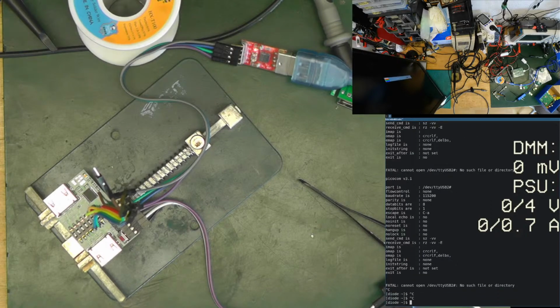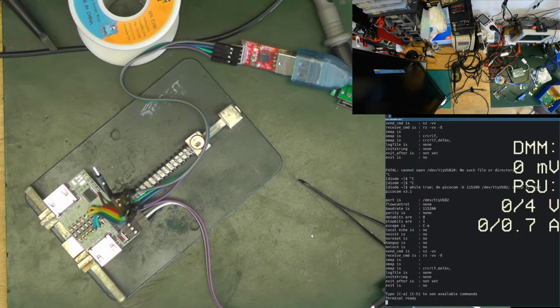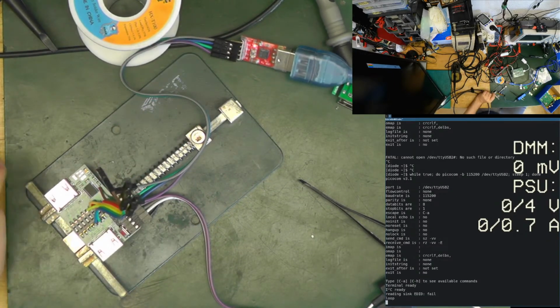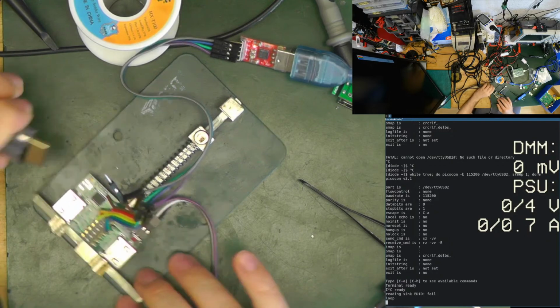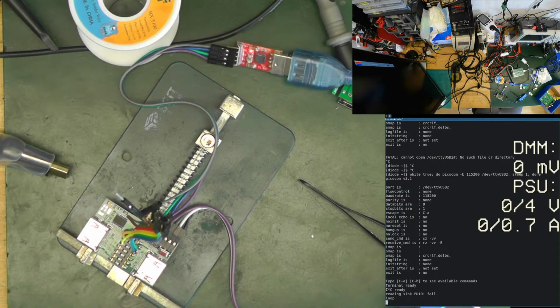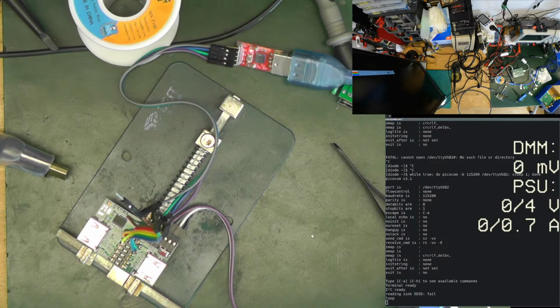This doesn't exist, that's normal. OMAP we don't need. We are not using AT commands. Okay. And here, every time I press the button, you should see we're in the loop. Reading the EDID fails. It fails because it is not connected. Actually, the LED should go on if it fails. Why doesn't the LED go on? This is already something wrong in the firmware. Let me check.